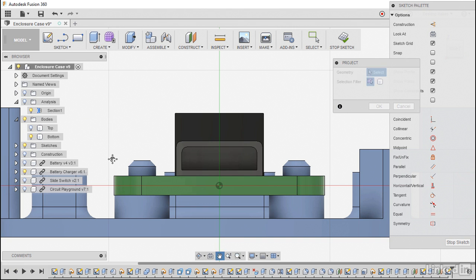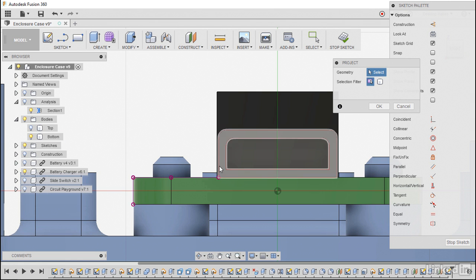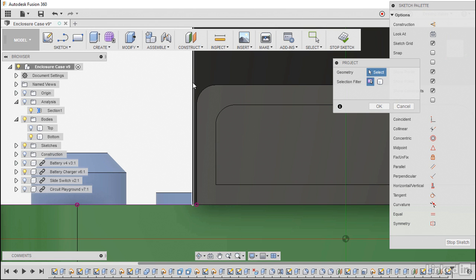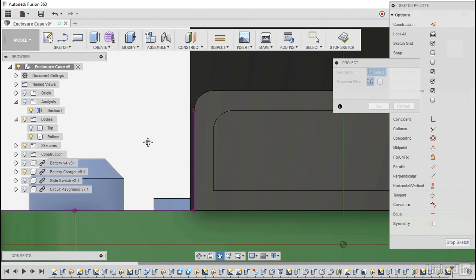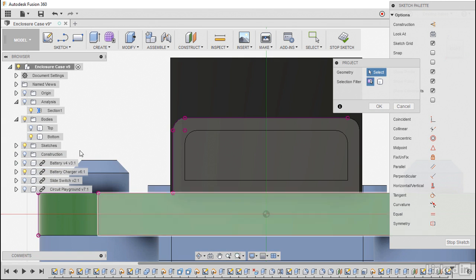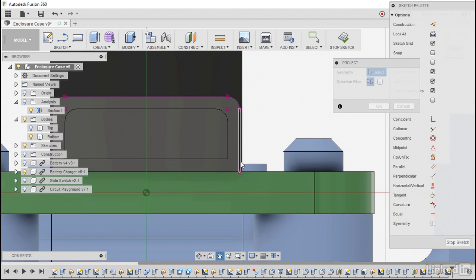And we're going to do it the same way by trying just to select the outer edge. So make sure you have it as specified entities instead of bodies selected. And we're going to just select these edges that we're going to need. So we'll start with the side. Grab the top here, and then we're gonna be careful here not to select the back portion here, but the front of this port there, and then we'll grab the edges here. And we'll just continue tracing this.